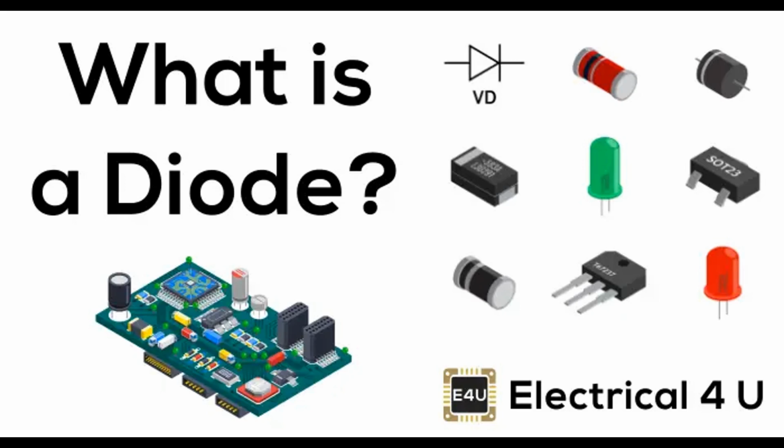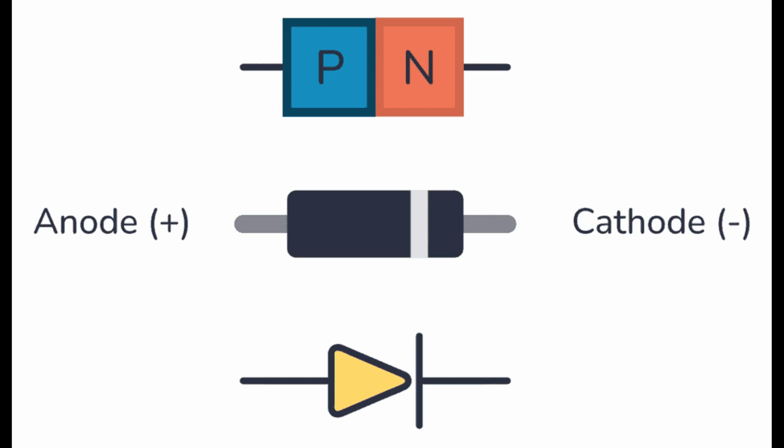Fuse bypass protection. In situations where a fuse might blow due to inrush current when power is applied, a diode can be used to bypass the fuse temporarily, protecting the fuse and the circuit. This is often seen in equipment with large capacitors.